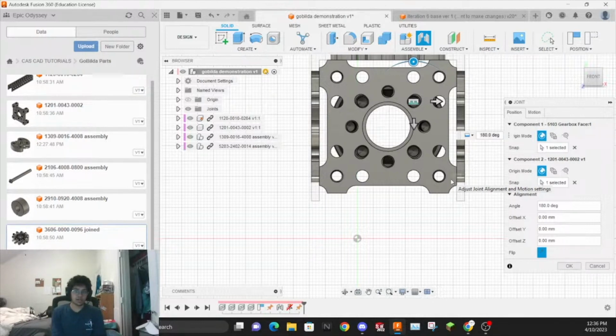So the motor does, the quad blocks do, and that avoids a lot of clunkiness and space wasting. It's very efficient. However, you can't put two threads together, so you can't put a nut on a quad block and then drive a screw through it because that won't work. Because the pitch between the one thread and the other will be all sorts of whacked if one is a longer distance than the other.